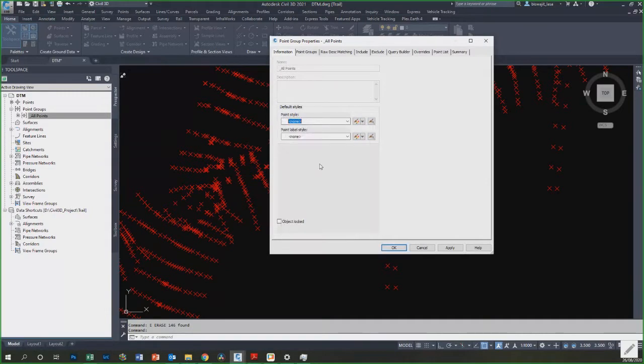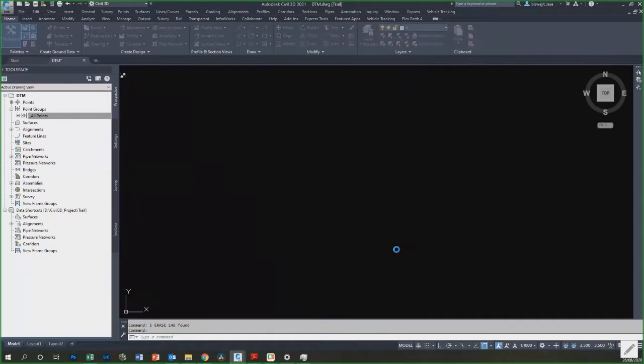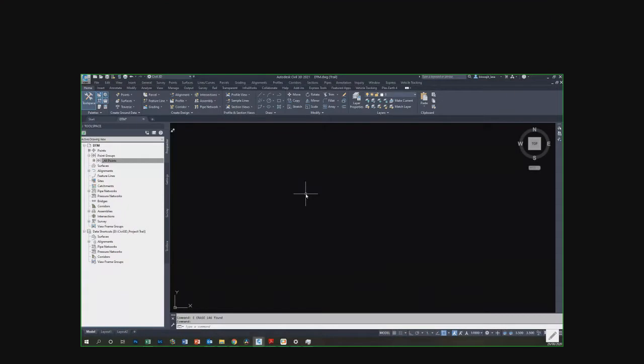I'll show you how to create them in some different session on styling. I'll take one session for the styling of this Civil 3D. In that, I'll show you how these point styles and whatever styles there are. Just get into this one first. Set both none, apply, and then say OK. All the points are in this particular drawing, but the display is off.